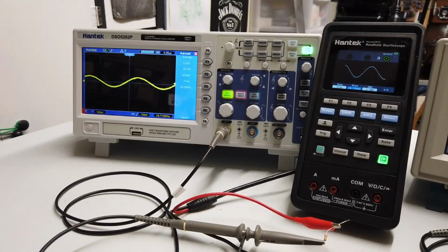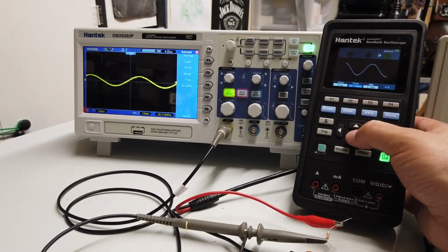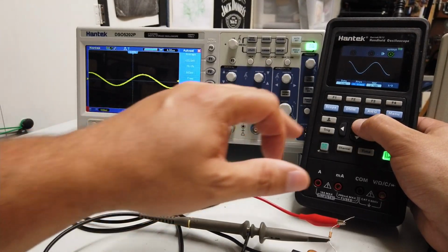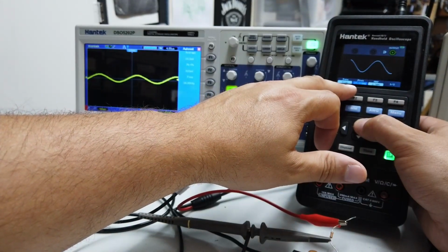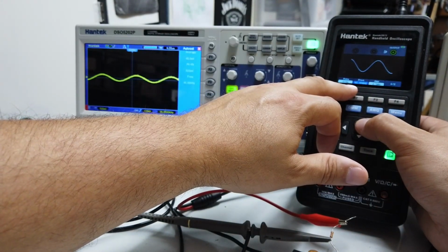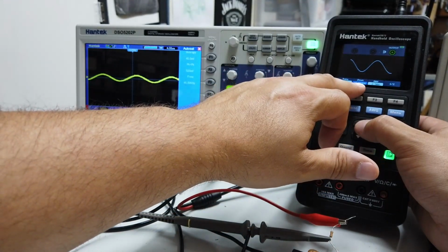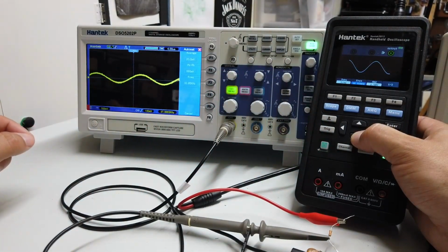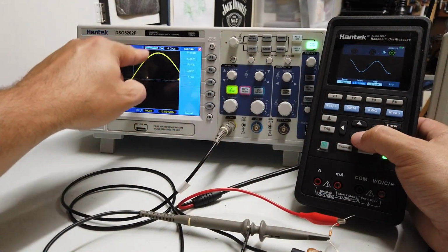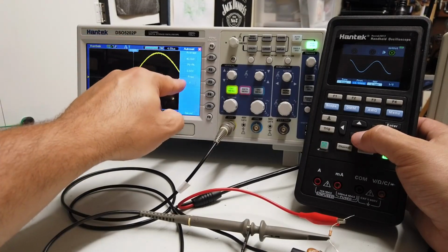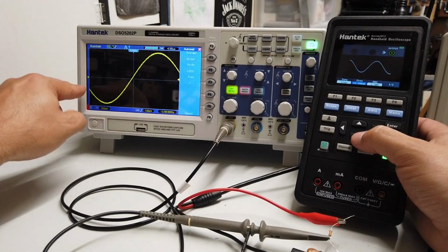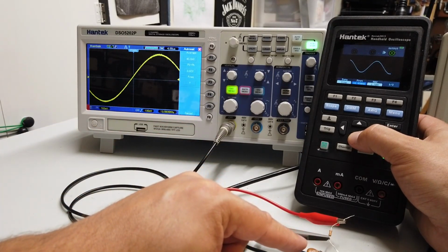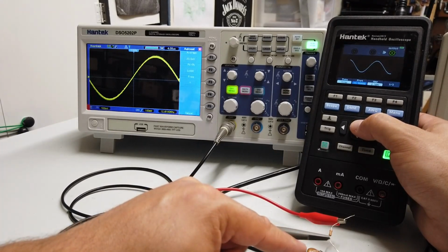Alright, so I'm hoping you guys can see this okay, but what I've done is I've set this up so I can press a button here and sweep the frequency, and at the moment I'm around sort of 30 kilohertz. So I'm sweeping the frequency now from 40 kilohertz, and we're going down 30 kilohertz, 20 kilohertz, and as you can see there's a sudden peak in the amplitude of the response. Effectively, that's where the tank is tuned. That's where the tank coil is tuned.